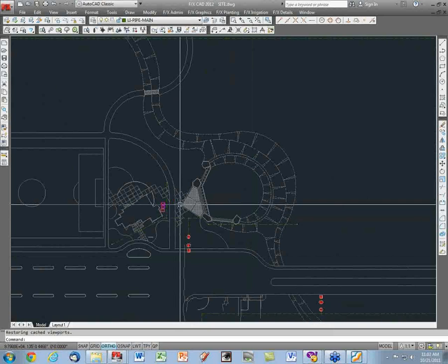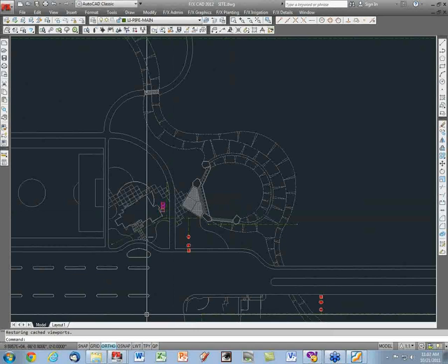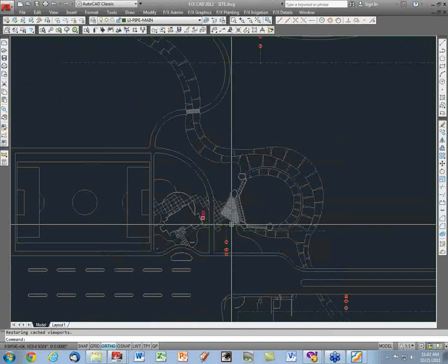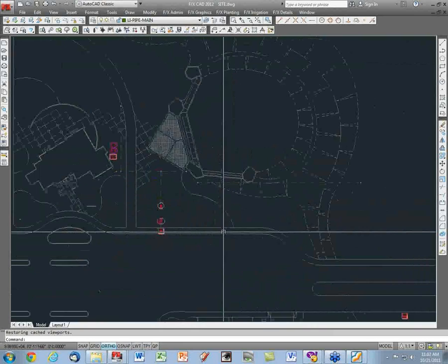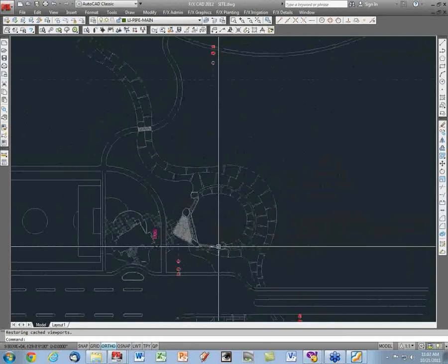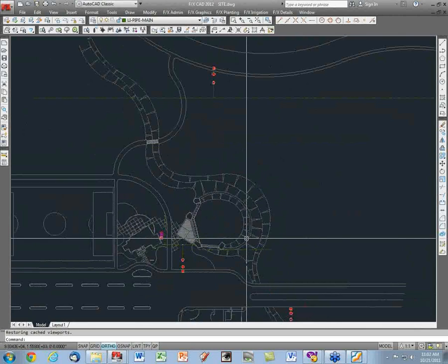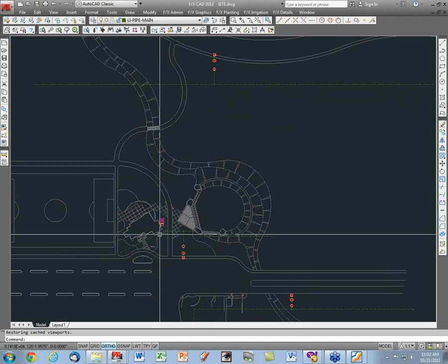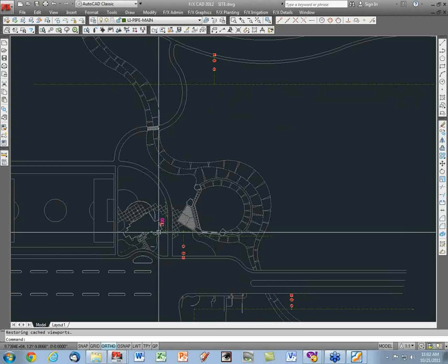Okay, gotcha. In regards to that, they asked, can you read two flow sensors individually on one controller, such as per program? Only if the controller is set up to have two flow sensor inputs. There are some that do that, but no. What the combiflow is doing is allowing you to read two or more flow sensors on the single input channel of the controller, so you can't read them individually.